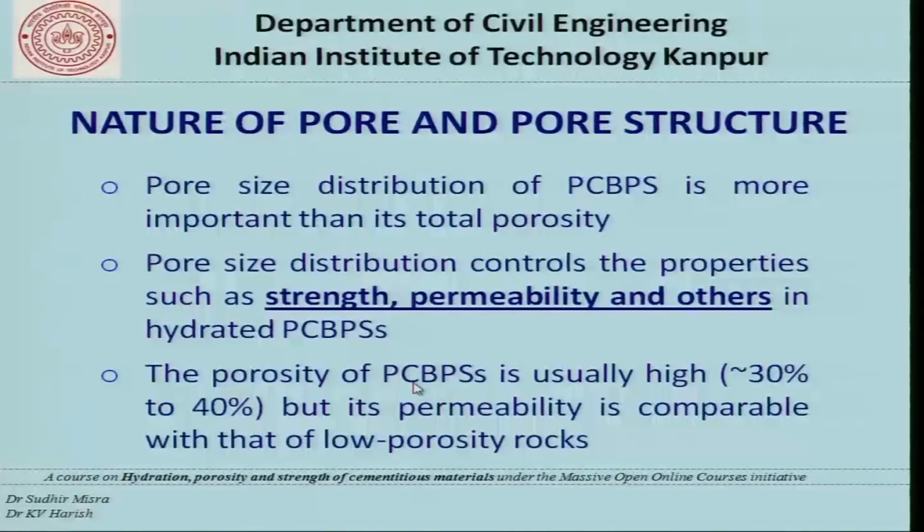The porosity of Portland cement based paste system is usually high, approximately 30 to 40%. But remember that despite having such high porosity, the permeability of these mixtures is very low and comparable to the permeability of rocks.